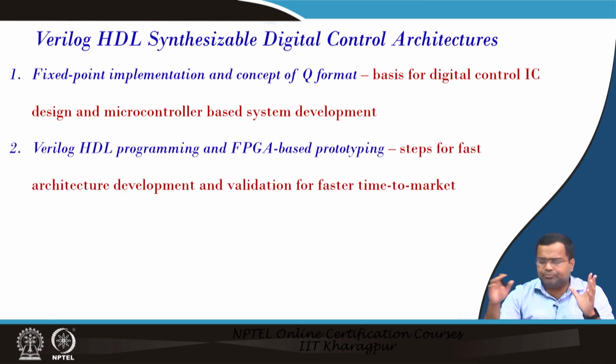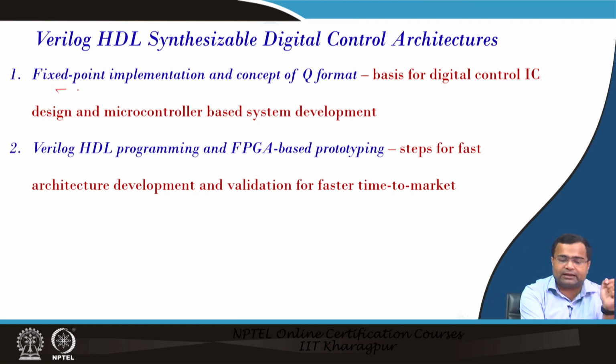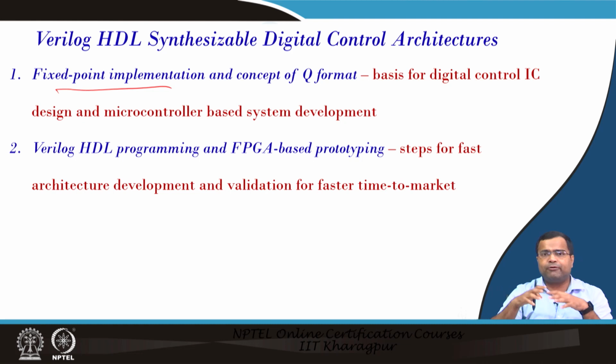Then, because most of the low power commercial products use fixed point implementation, but if you go for a floating point processor they are quite expensive and power hungry. So, depending upon the application requirement, if you are talking about just a battery charger, onboard charger, or a power management IC, most of them go by fixed point.